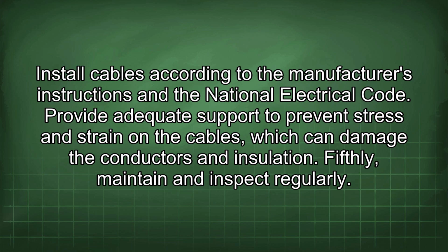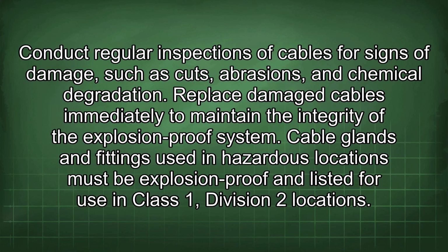Fifthly, maintain and inspect regularly. Conduct regular inspections of cables for signs of damage such as cuts, abrasions, and chemical degradation. Replace damaged cables immediately to maintain the integrity of the explosion-proof system.